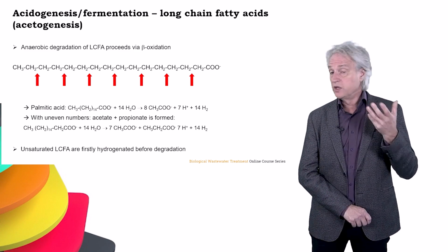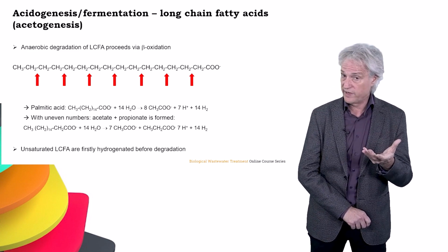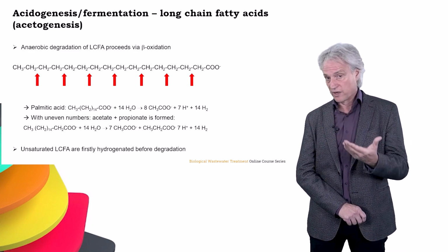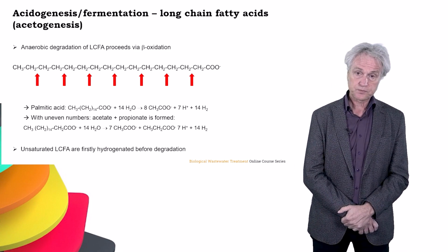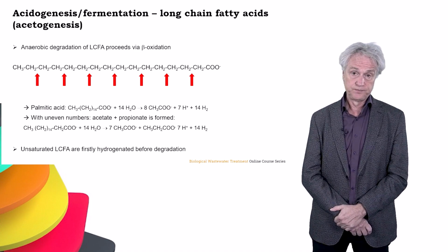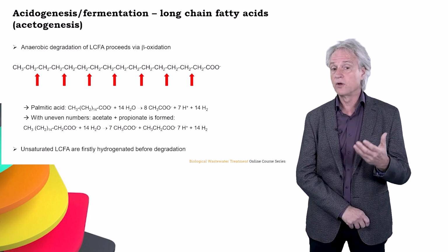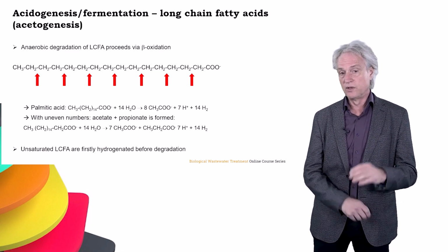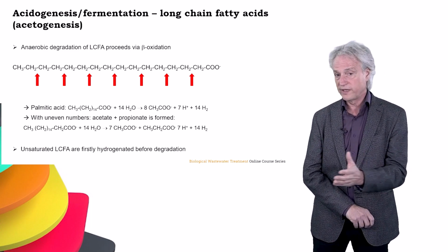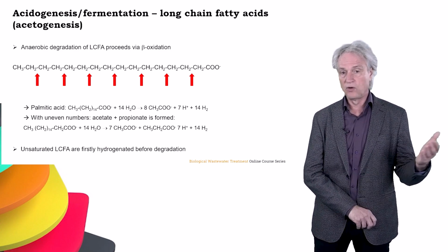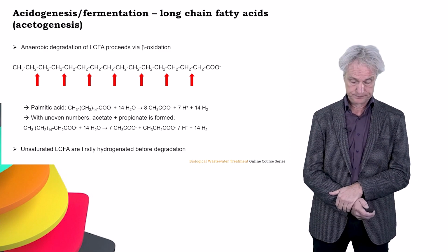Now, what you need to know if you treat sewage is that this reaction is really a difficult reaction. That means if there's a lot of fats, then I'm sure that these fats may accumulate in your system, particularly if the temperature is low. Now, in addition to the saturated long-chain fatty acids and fats, we also have unsaturated LCFAs. They have a double bond, and they first need to be hydrogenated before they can be degraded. For instance, oleate will be first converted before it's being degraded.